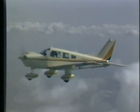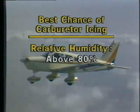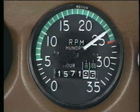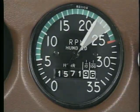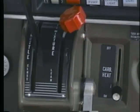Although carburetor icing can occur over a wide range of conditions, it is most likely to form when the relative humidity is above 80% and the temperature is below 21 degrees Celsius or 70 degrees Fahrenheit. In most training airplanes with a fixed-pitch propeller, the first indication of carburetor ice and the subsequent power loss is a gradual decrease in engine RPM, which may not be readily noticeable. If this situation occurs, you should apply carburetor heat. This routes heated air into the carburetor to melt the ice.